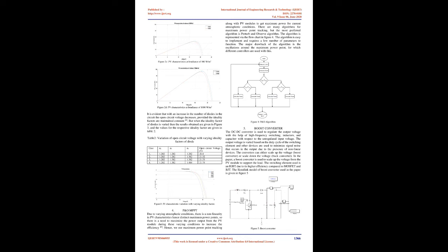2.3 Three-diode model. In the three-diode model, there are 3 diodes, diode saturation, series resistance, parallel resistance, and current source. The mathematical model for a three-diode model of a solar cell is given as, where IPV is the photon current generated due to incident light, IO1, IO2, and IO3 are the reverse saturation currents of the diodes, which in general are kept equal. VT1, VT2 and VT3 are the thermal voltages of the diodes, and a1, a2, and a3 are the ideality factors for the diodes.